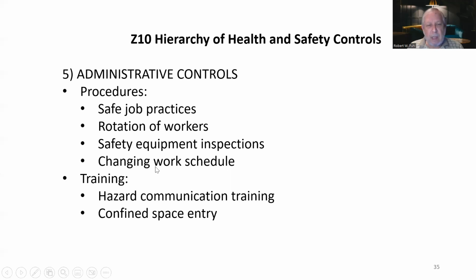Under the safety equipment inspections, what do you think that involves? I'll give you an example. Equipment probably has e-stops on it. Does anybody ever check to make sure those e-stops work? You only use them in an emergency, right? Most equipment, you don't use those to stop the machine, although some people do. But do they all work? How do you know they all work? So periodically they should be checked.